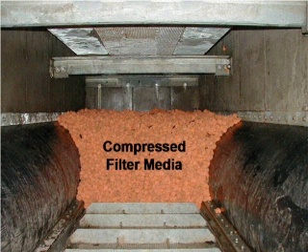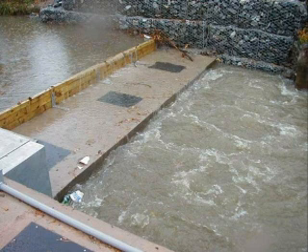The flow path of the wet weather are these 2 red lines. The first 2 mgd actually goes back through the UV system and out. When it goes above the 2 mgd, the filters will handle about 10 mgd, and part of it goes through UV disinfection, and part of it goes through just the filter.